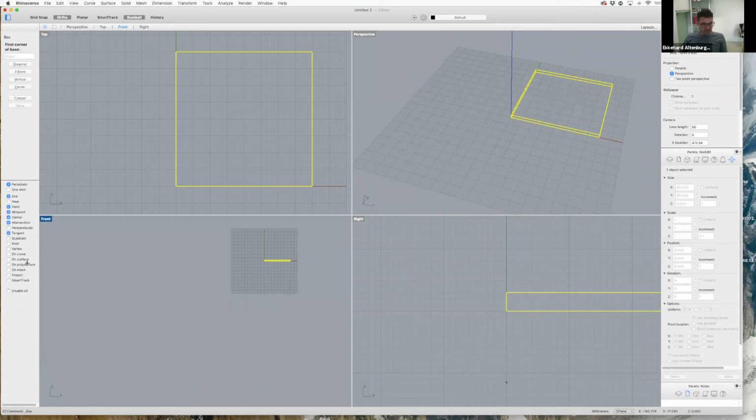You can also decide what you want to snap it on. Usually it comes with areas that are very common, like it snaps to an end or a point or a midpoint. What does that mean? At the moment here, you get that little sign saying end. It snaps to the end point. If you move your cursor to the middle, oh, look, it snaps to the midpoint. So that's quite useful.